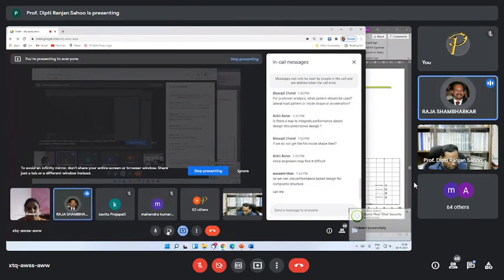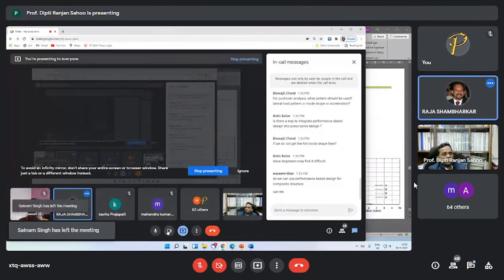Because in the 2001 earthquake, the Bhunga house was saved near the Bhuj earthquake epicenter. We are not from structural civil engineering, we are from architecture. For architectural students, I am going to teach how plan form and built form can create structural symmetry so that minimum damage occurs during the earthquake.